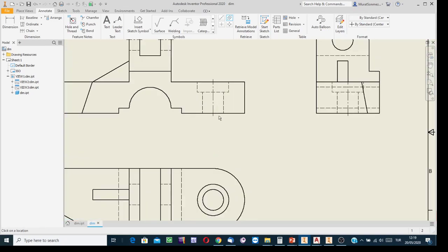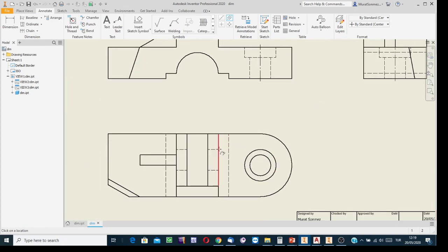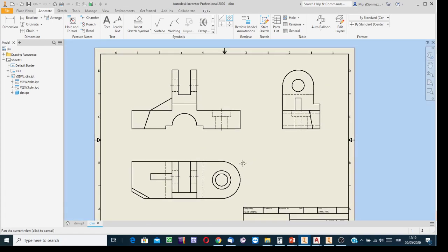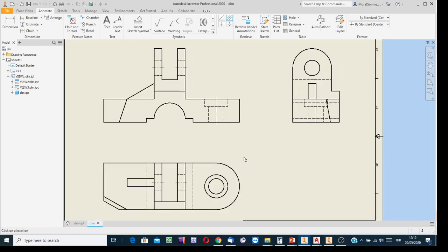A reader looking at the image and finding a rectangle with a longitudinal axis can directly conclude that it is the image of a revolved feature. On the top view, show the limits of the holes to highlight that those are revolved features, with the longitudinal axis. I think it is okay.